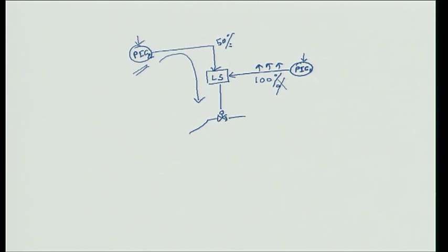So, what happened was, when this output increased above 50%, control passed to this controller, and because control has passed to it, this other controller is uncontrolled. To get control back, it says move the valve, and the movement of the valve will be in the direction that takes this away from this.